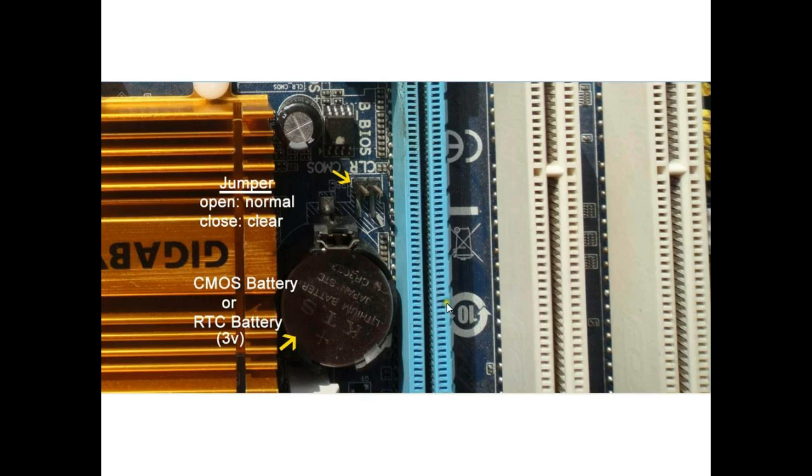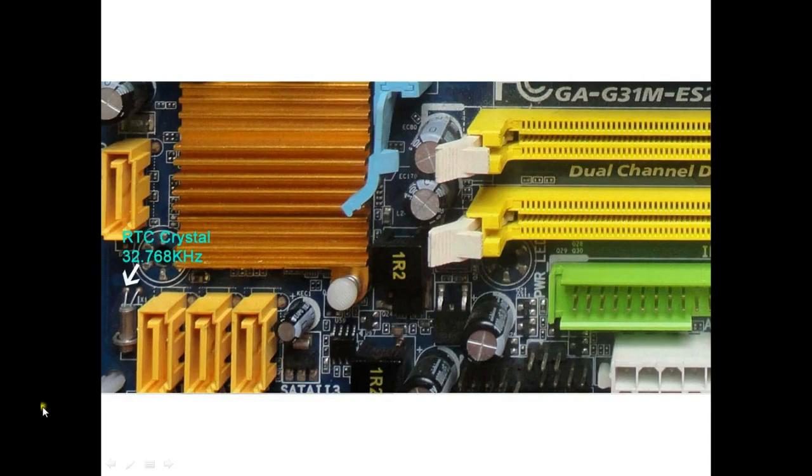This battery is used to give supply to the RTC circuit, that is real time clock circuit, to maintain the system date and time in sync even when the PC is switched off. So here we have another crystal whose frequency is 32.768 kilohertz near to the south bridge. We call it the RTC crystal.